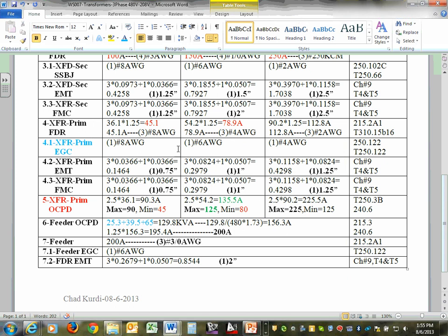So you get yourself number 8, number 6, and number 4. And then now we have 4 conductors. Actually, 4 of them number 8 for the first one. Based on the 3 for the 3-phase and the equipment grounding conductor, I can size my conduits, EMT or flex. You can see how we size the EMT and flex.